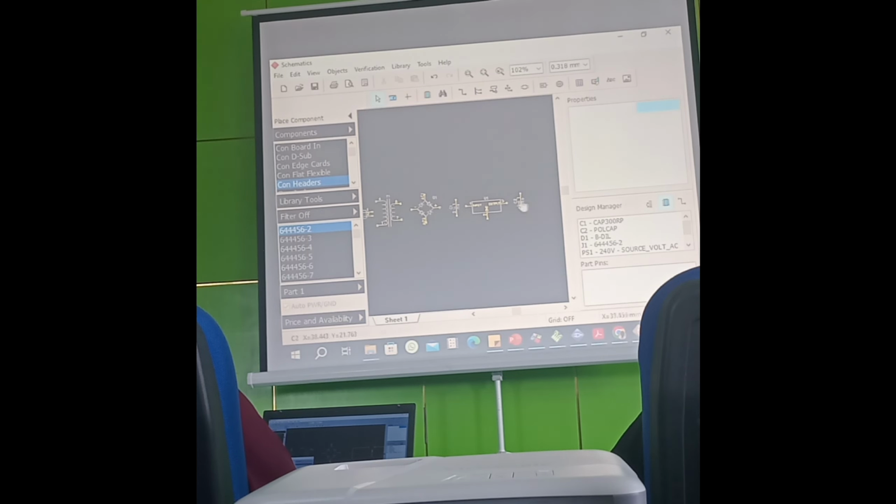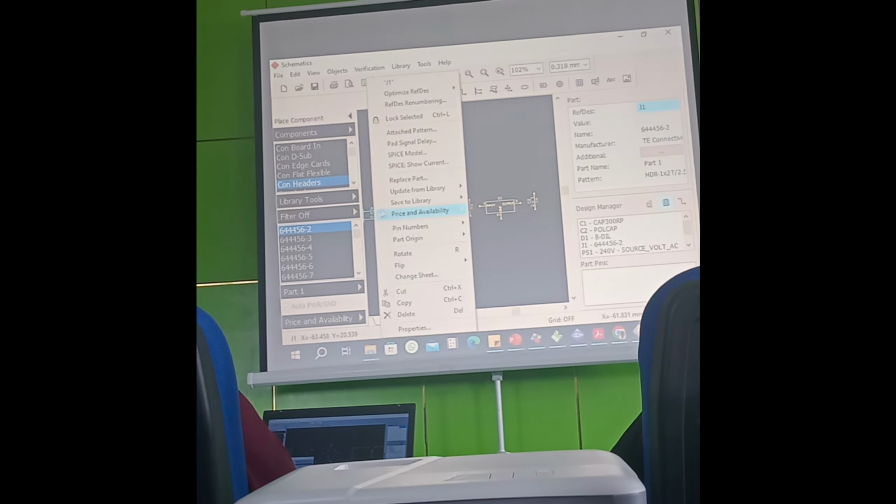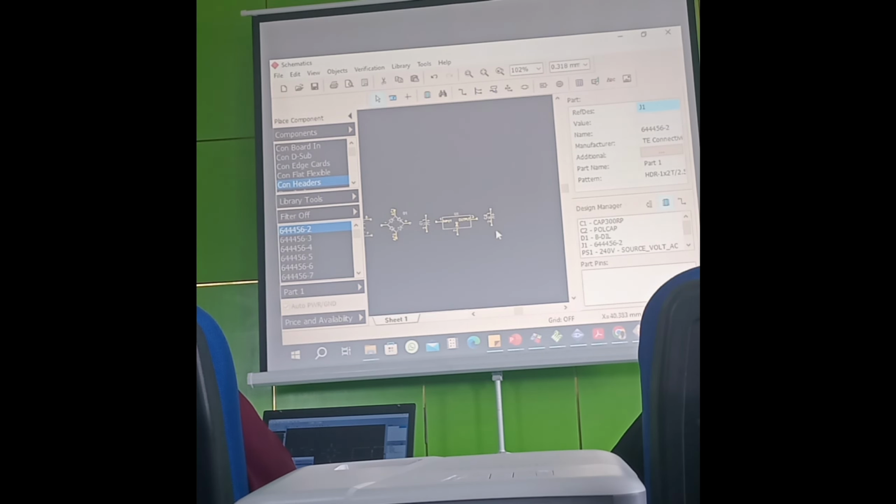Then our voltage too, at the source. This is the output voltage here. This is the filtration capacitor. We should have another connector too at that point for us to get our 5 volts for the output. Another connector to here. So now, after placing all our components, the next thing for us to do is to